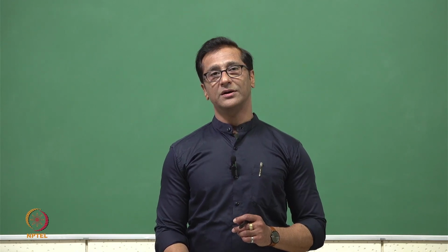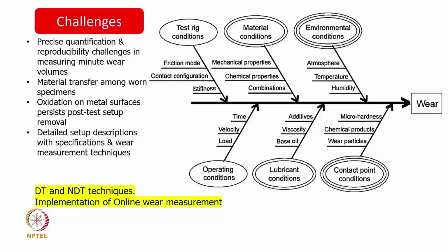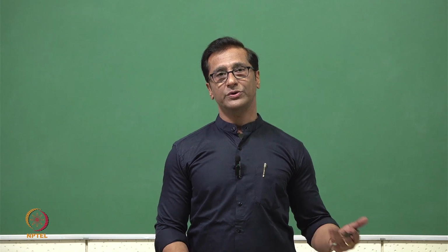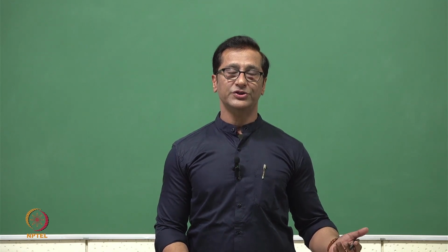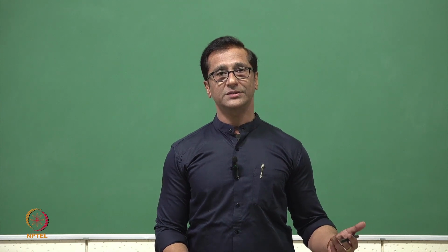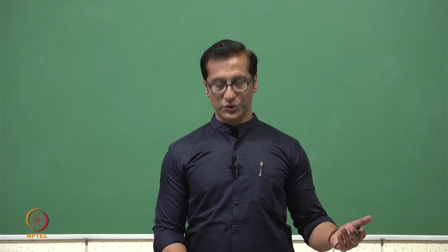One more thing is, can we go for in situ measurement? In my view, in situ, online wear measurement is the best way to do it. We have destructive testing, we have non-destructive techniques, and there is enough literature, and I don't want to go into detail, but inline measurement will always be preferable compared to post processing and analyzing later. And particularly when we talk about artificial intelligence or machine learning, we will be going with the inline measurement instead of post processing.